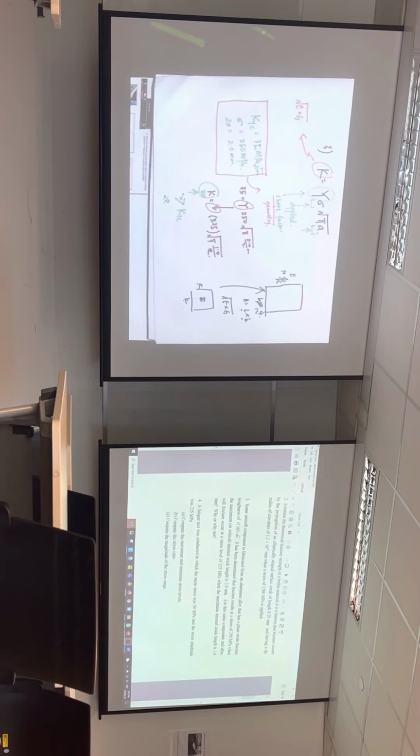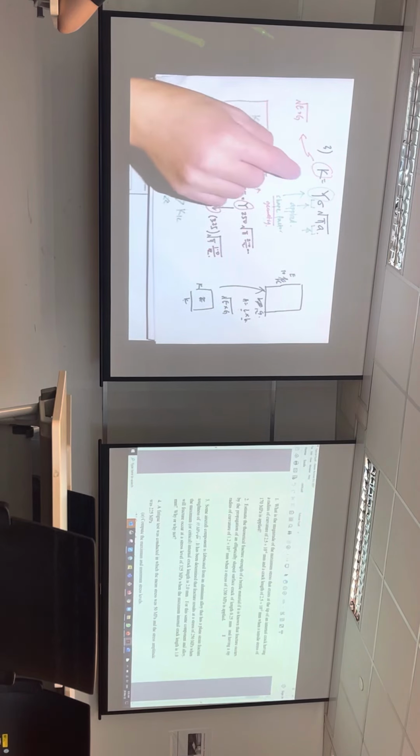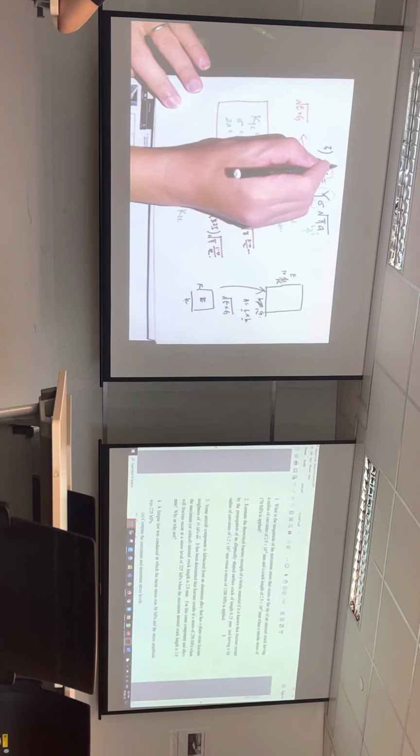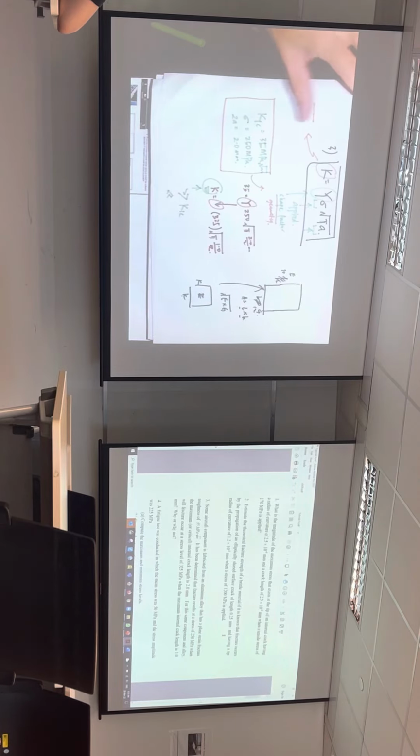So these are actually on a simple crack with something inside. There are two major equations that you need to deal with. Just now, the stress amplification, in terms of how stress has been bumped up. This one is to test on failure based on material property. This is also a very simple equation, and I expect you to remember it: K equals Y stress square root pi a. I expect you to remember. I will not give you this.